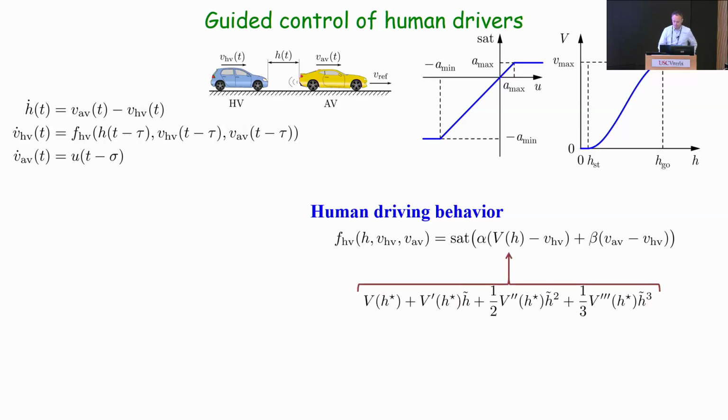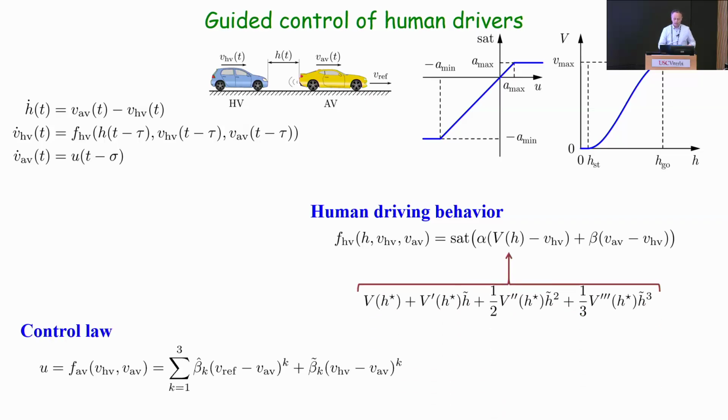After all, there is approximation up to whatever order you want. And then, interestingly, you can also set up your control design in a very similar form, right? You can say, I just set it up as a Taylor expansion, and my job is to find these different gains in this case. Okay? So if you do this, your job is to make sure that the unstable limit cycle doesn't exist, right? So you can choose these betas such that the reduced order dynamics is simpler, okay?